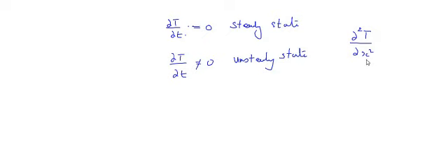So to solve these kinds of problems, we bring in some assumptions. One simple assumption is that we neglect the internal temperature gradient. There is no temperature gradient inside the body, which means there is no change in temperature inside it, and we consider the body as a single lump. I'll explain all these things step by step.